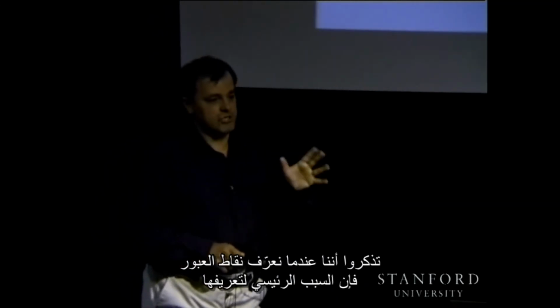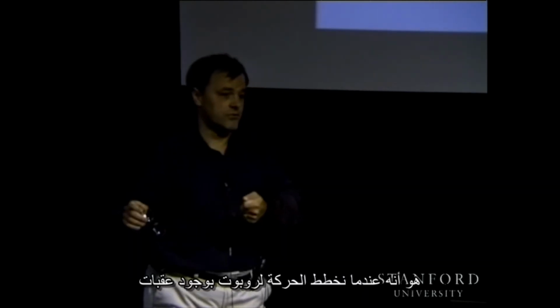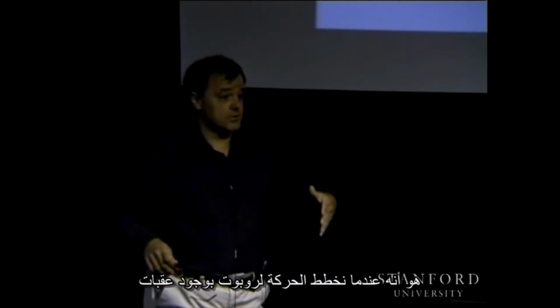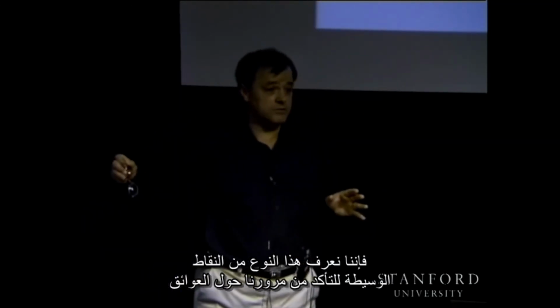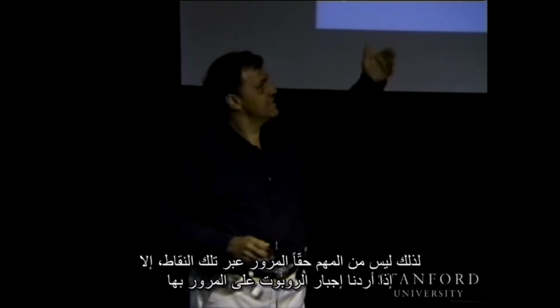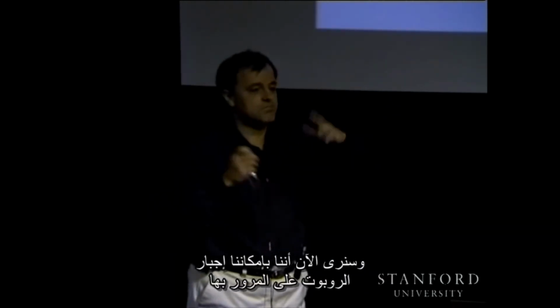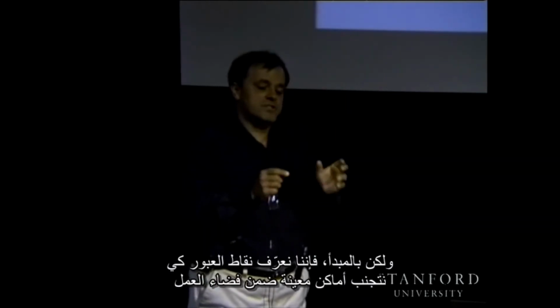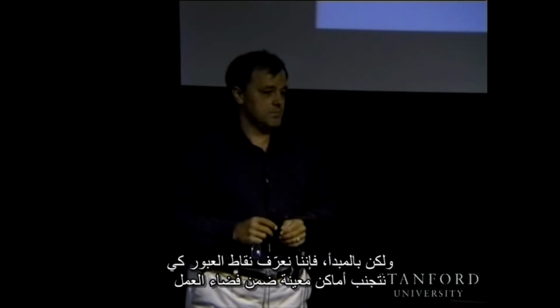Now remember that we introduced these via points. The main reason really to have these via points is when we're planning a motion for a robot with obstacles, we want to introduce this kind of intermediate points to make sure that we go around the obstacles. So it's really not that important that we go through the exact points unless we want to force it, and we'll see right now that we can force it. But in principle, the via points are just to make sure that we avoid certain spaces in the workspace, okay?